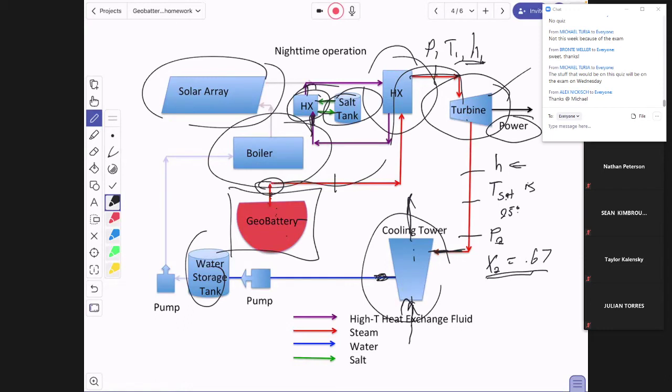If you understand those 5 things and are able to apply the equations to get the work out, work in, the velocity coming out, and understand that the enthalpy is equal on either side of the throttling valve, if you've got those concepts down, you're going to do fine. Because everything that we're talking about from here on out is just a combination of doing these energy and mass balances around different devices.